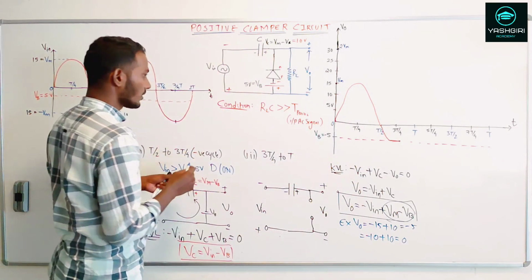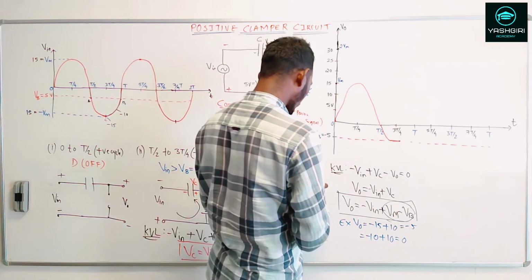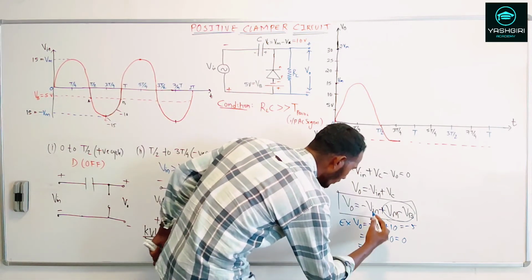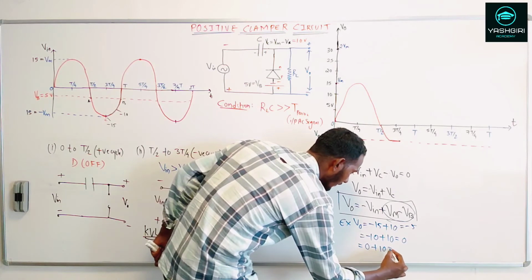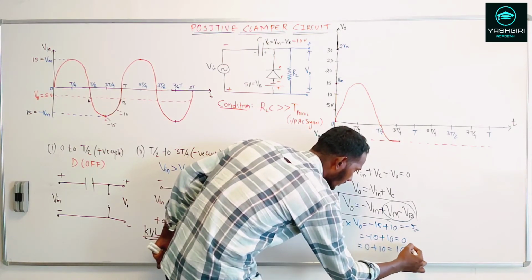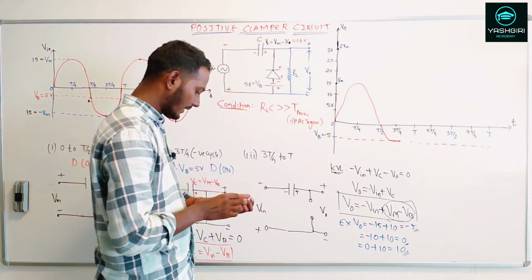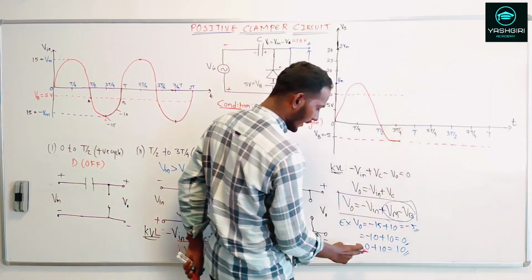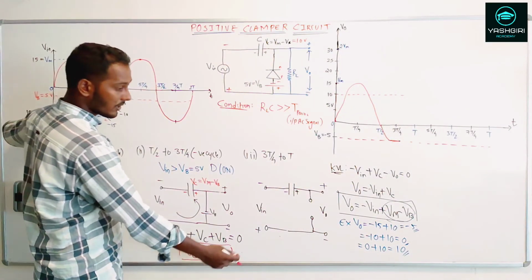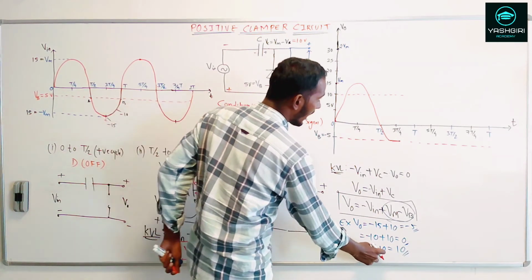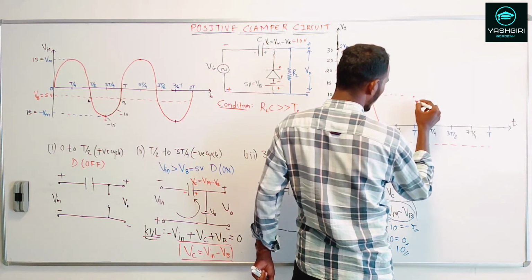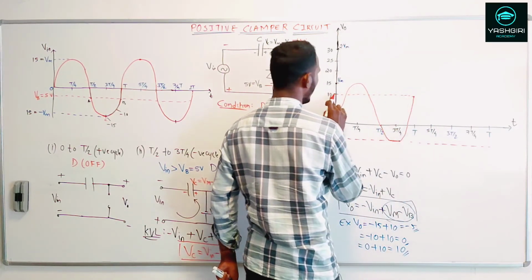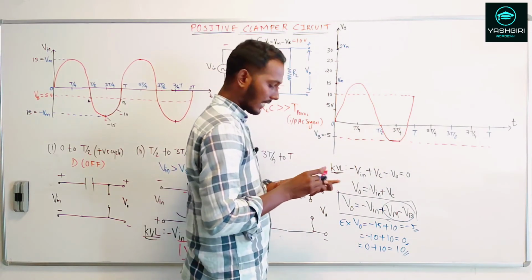0 volts, right? So here if you trace the output waveform, at t equal to 0, when I substitute V input equal to 0, 0 plus 10, that will give me 10 volts. Now if you plot these points on the output, this is my 10. At t, I know the input signal is coming to be 0. This is happening at time t. So at 0, I'll get a 10. So at this point t, you will be getting exactly like this. This is happening for 10 volts at time period t. That's the corresponding time period t.